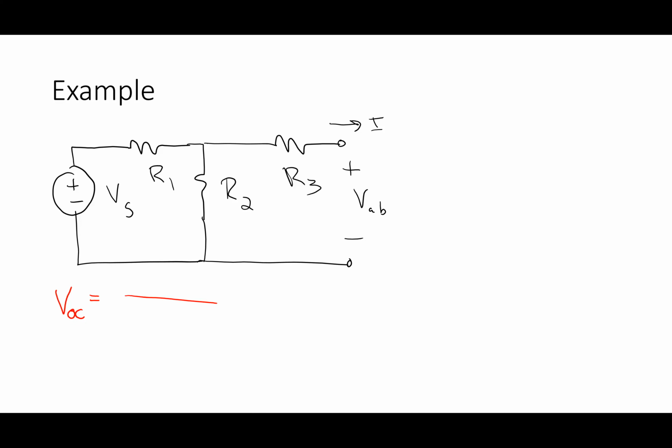I don't mean to squash Eli's enthusiasm here, but this is a voltage divider. With a voltage divider, as Tony said, R1 plus R2 goes on the bottom. My way of thinking of it is that's the current that's flowing, and then to get the voltage, it's that current times R2.